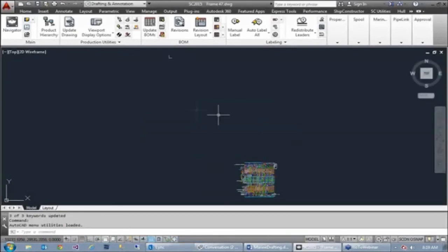So it's generated this drawing, and I've got this X reference that is the whole unit. And so it gives you an idea of if I wanted to orbit around, I could. I'm not going to do it just so it doesn't bog down my system here. And in this case, I've got a little placeholder where I'm going to put my output so that it lies within my viewport for my layout space that I'll show you in a couple seconds here. So really, this drawing has no special information other than what's in a regular production drawing currently, and I'll show you going through the process. But again, you typically set up some settings in the template.